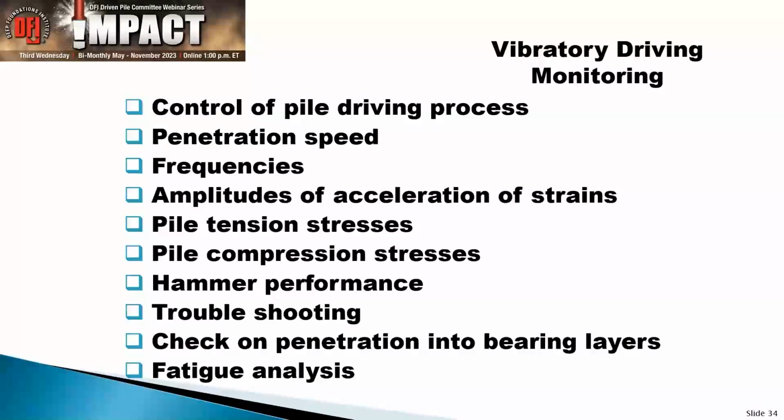When you have a pile that's being driven with an impact hammer, you may have maybe a couple thousand blows, but that's about it. But in vibratory driving, you have already 1,000 cycles within a minute. And it means that your total number of cycles is much, much higher, because it's not unusual that it takes about 25 minutes to drive a pile to penetration depth. So you talk about 25, 30,000 cycles.